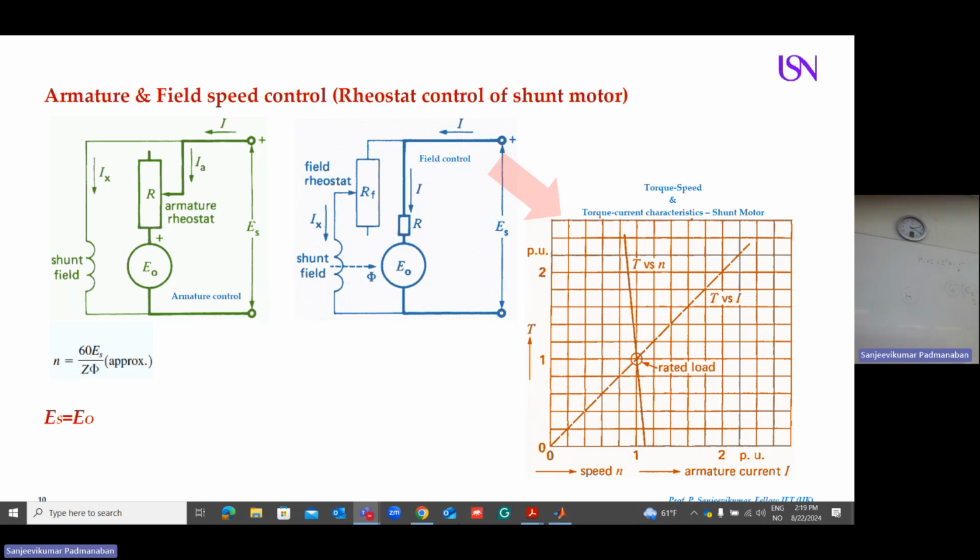So the kickback effect is nothing but, when you apply rated power to your electrical machines, in the beginning, a transient period, a short time, it generates very high current. You know the relationship: high current, high torque. That's why you get a torque greater than 100%, near 200%, for a short period of time. Then, as you increase your speed to near the rated value of 1500 RPM, you can see the torque is almost near zero.